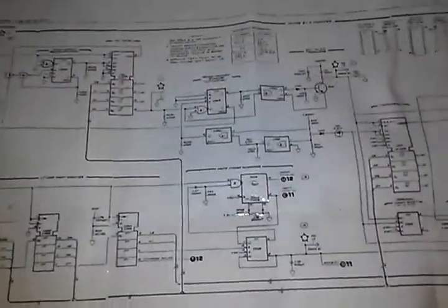And originally, when I was diagnosing this, I had made the comment that I think what was happening is that the high slew rate in the phase detector, which is not this circuit, it is schematic number 11 if you refer to the service manual, was not being activated. Essentially, what the circuitry thought is that it really was only moving 100 hertz. But in actuality, the PLL was moving 6 megahertz. And that's why it was taking so long to obtain a lock.